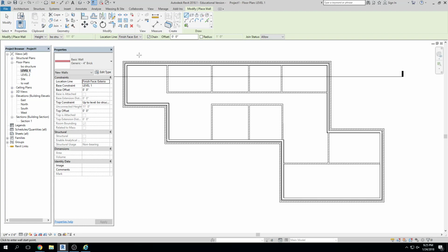And this is something that you're going to see again and again in Revit, this procedure, right? In Revit, there's not a create a new wall type button, and there's not a create a new door type button. Boo, did you say boo? There should be a button. But then, I mean, yes and no, because if it's a brand new wall, you have to define it from point 0, right? And what actually happens in Revit is you take something that is similar to what you want to create and you alter it to what you want it to be, right?